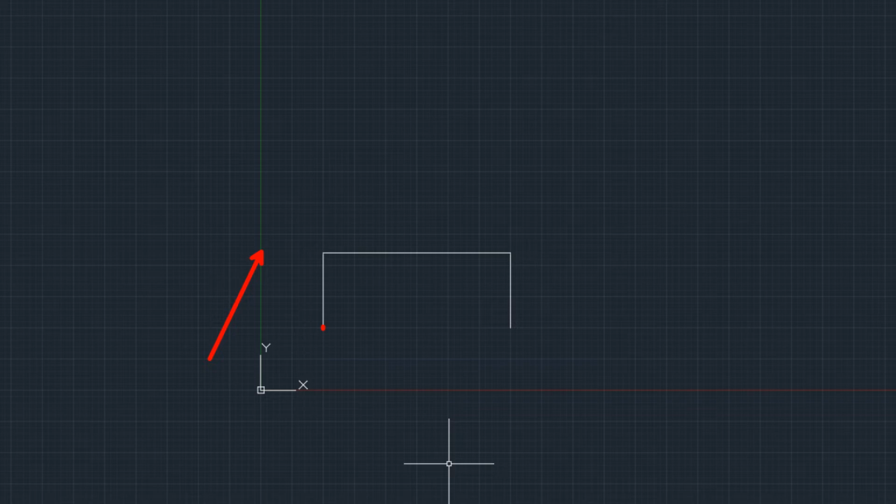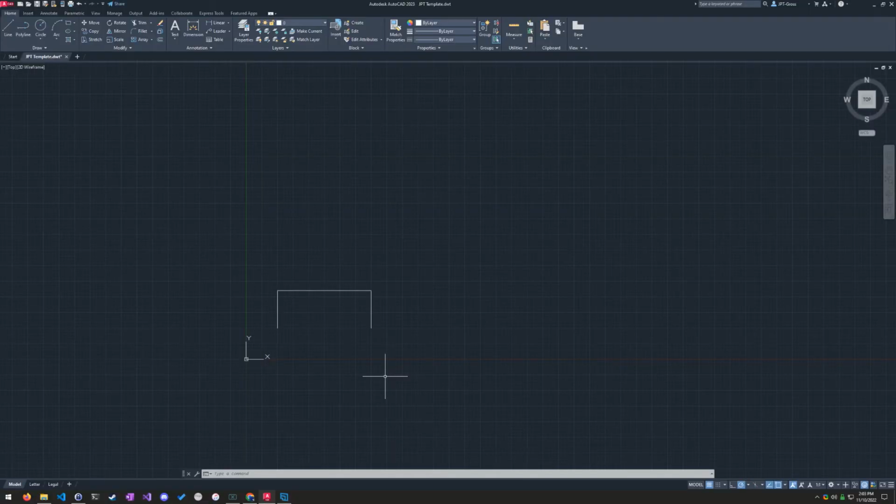So it'd be touching the green line. And then 15, 0 would be there. And then 0, -6 would be like way down there. So we didn't do the actual coordinates that they are on the grid. Instead, what we did was we put in what's called relative units, meaning relative to our last location, where do we want to go? Well, 0 left and right, but positive 15, which is to the right, and 0 up and down. And then 0 left and right, but down 6, which was where we got that -6 from, right?